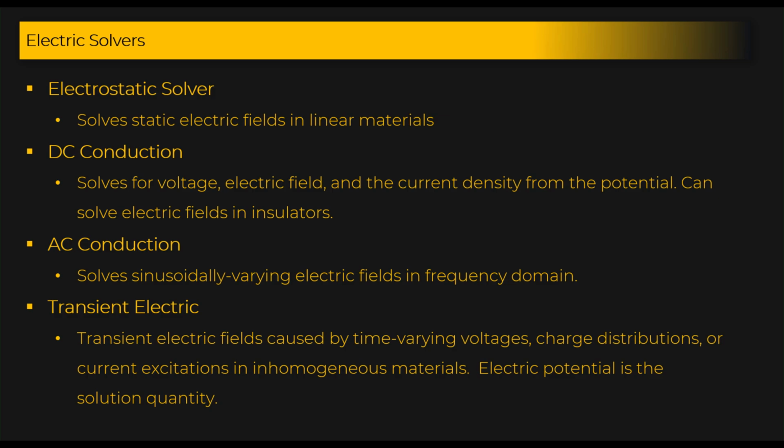So now about the AC conduction. The AC conduction solver helps in solving sinusoidally time varying electric fields, and it solves in the frequency domain. The AC conduction field solver allows you to analyze both conduction and displacement currents due to time varying electric fields in the conductor, and also in a lossy dielectric. The user can analyze current distribution, electric field distribution and potential differences, and also the CG parameters. For instance, the admittance matrix associated with the structure can be computed using the AC conduction field solver. Here is a basic overview of all the solvers and when to use which one.